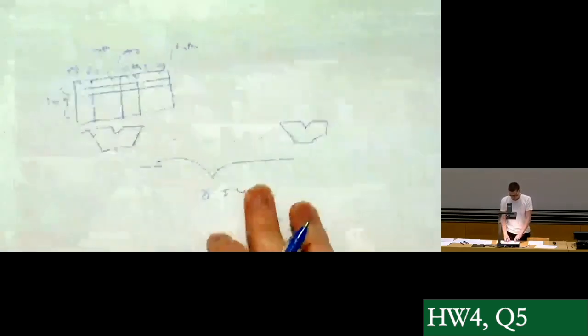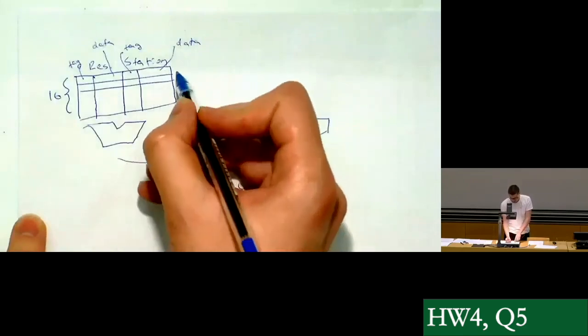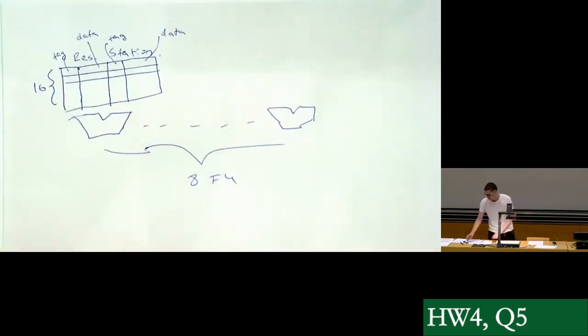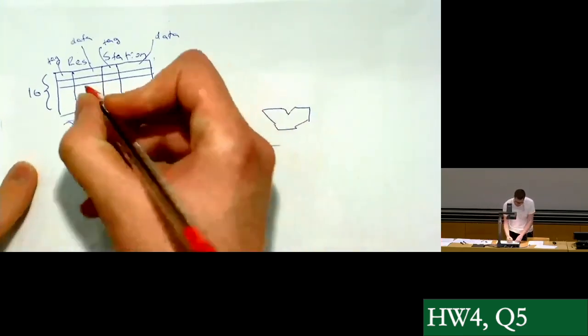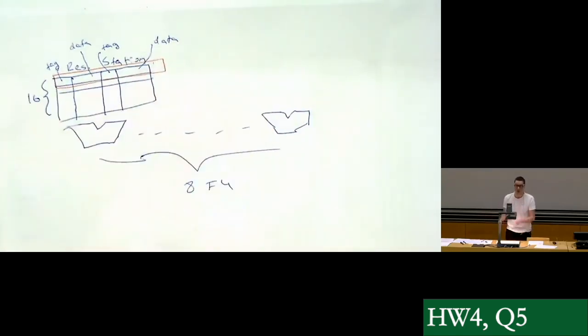So if you go back here, in a single reservation station entry, we have two tags, right? Because we have 2 source operands. And so we will need a comparator for each tag for each functional unit, right?